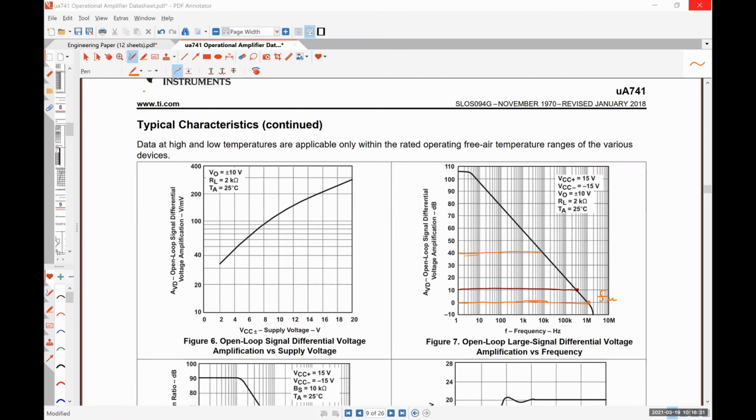So if I run my simulation right now, I have a 50 kilohertz sine wave, and I look at my input signal and my output signal. I can see that they effectively match, right? This is a simple unity gain buffer, so I should expect a gain of 1. At a frequency of 50 kilohertz, everything seems okay.